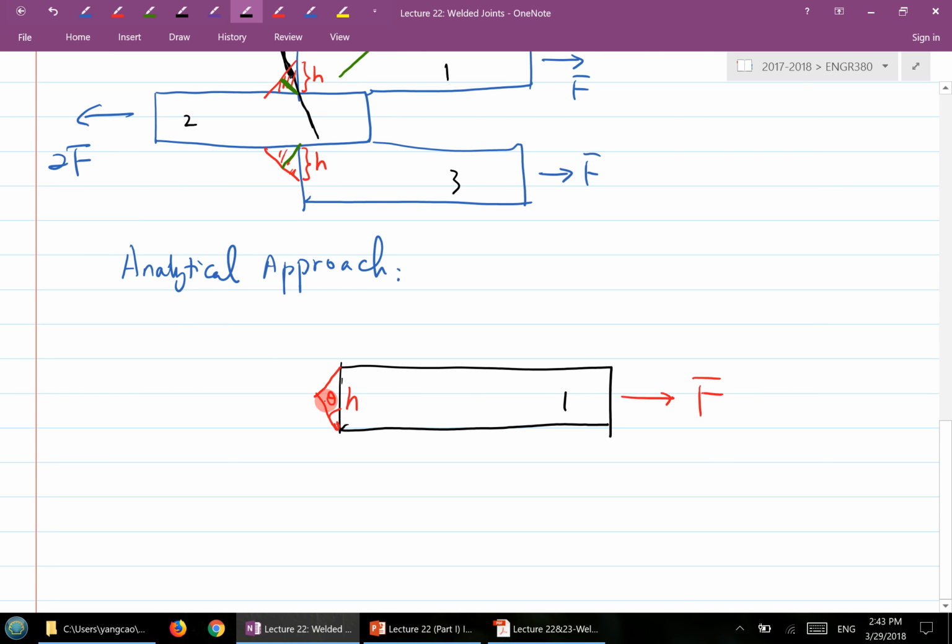Once you do the cut, imagine, this is a cross section, isn't it? You cut it through the joints. So I can label a free body diagram here. Let's say I have a force pointing this way, call it Fs, and a force normal to the surface, call it Fn. This angle is still 45 degrees, the top one here is 45.